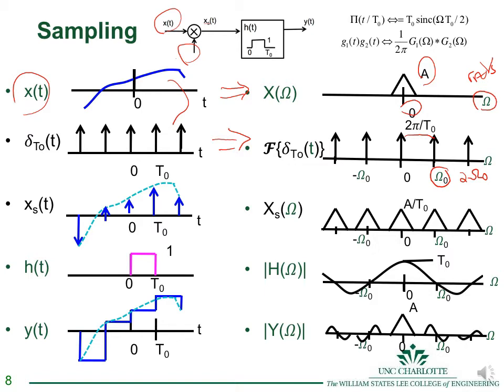And so the easiest convolution, if we recall, if I have a box with an impulse response h of t, its output is the convolution of h of t with the input, but if the input is just an impulse, a delta function, then the output is just h of t. So if I delay that input, of course, the output is delayed. And if I double the input, the output is doubled.